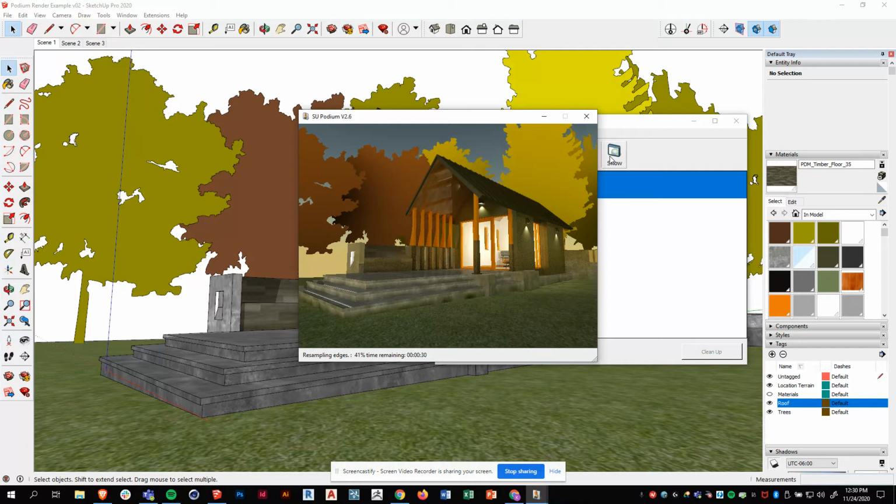You basically have this ability to get some reasonable spotlights in there with a nice gradient. Maybe those even are a little intense and I want to dial those back a little. Also, you get some nice point lights in there to really bring that whole interior to life. So point lights, spotlights, and light emitting materials, those are really all you need to do something really cool with your SketchUp models.